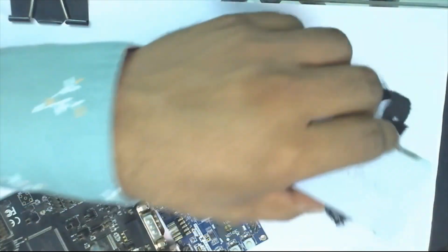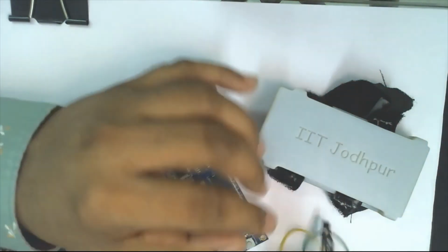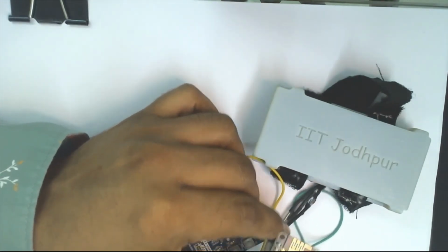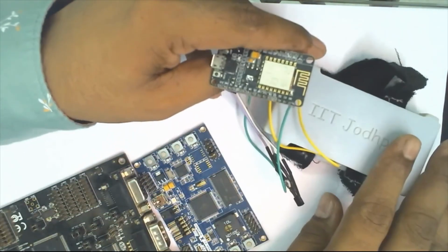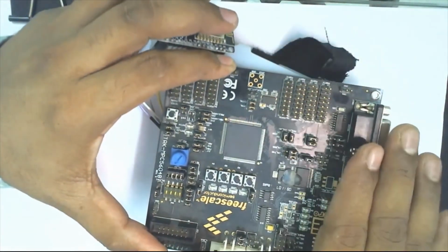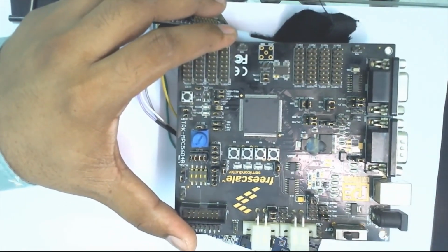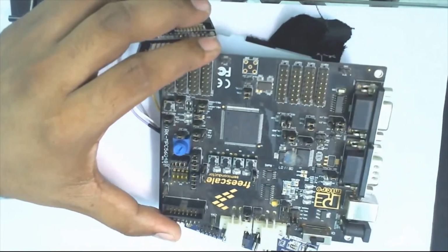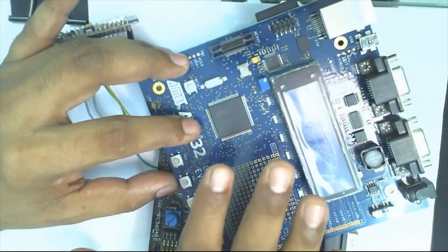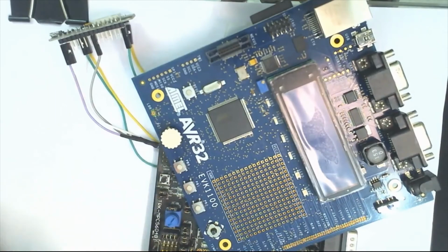For example, we may have available C code libraries, available diagrams, or code snippets for developing an 8-bit microcontroller system, or what we call small scale embedded systems. But if we move towards the medium scale, the complexity increases. Some things we can use like IPs or application specific standard products, or ASSP, or TCP/IP protocols and all those things. But as we move towards this one, we may not have things available at hand, and we may need to start from scratch. So this is how the division of embedded systems is done.